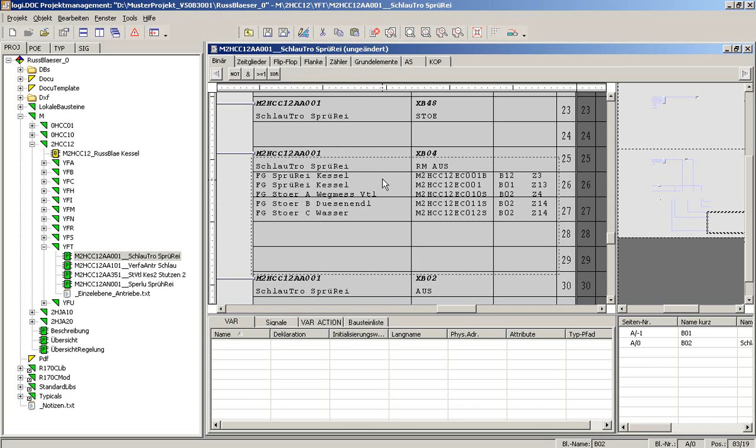As cross-reference information, you can see here the function group identification as the power plant identification of the target sheet position. You see the long name of the sheet on which the signal resides, and here you can see the short name of the sheet and the line number belonging to the position of this signal on the target sheet. For further editing and processing of the function plans and for tracing the signals within the function plans, the cross-reference of these signals is really important.